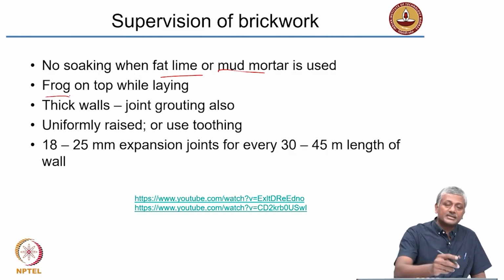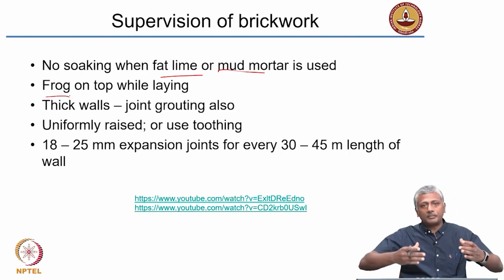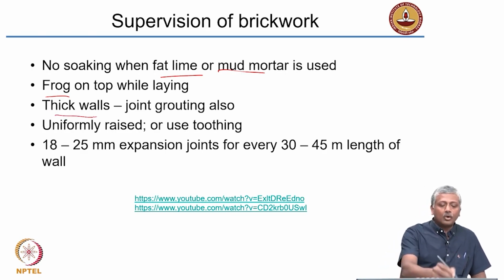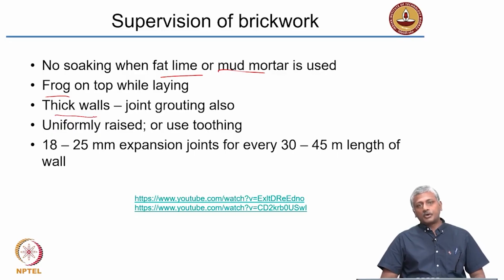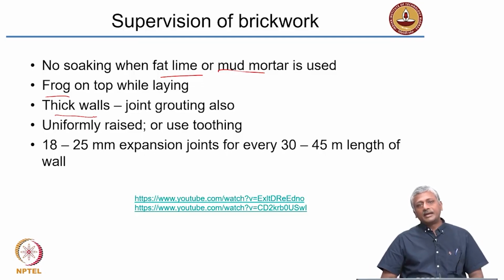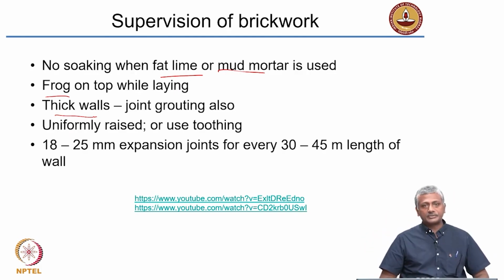The frog, that is the depression on the brick where the name of the manufacturer is there, typically is laid on top while laying. That is just for uniformity. In thick walls, it is possible that you may not be able to have proper jointing or joints between the bricks, and many gaps may be left over. In such cases, you have to ensure that at the end of the wall construction, you do grouting to fill up all those gaps. So, in thick walls, we typically do joint grouting.